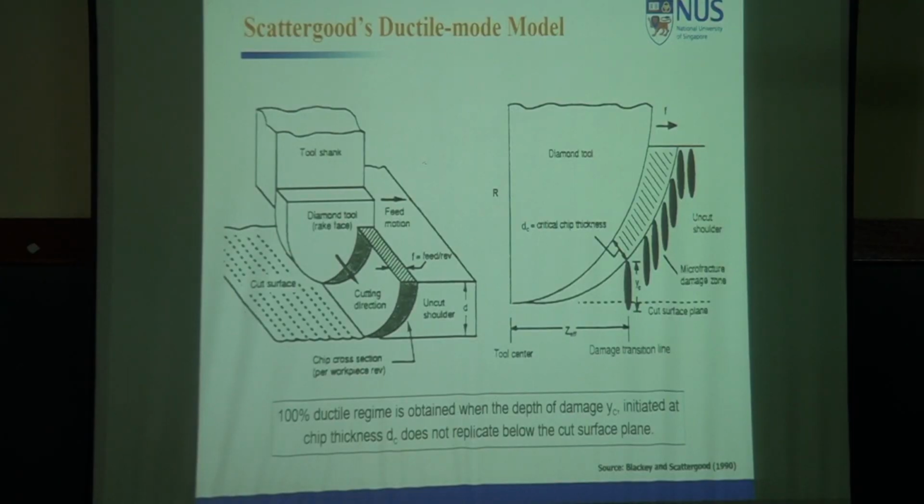In brittle material, you have to control the feed rate and depth of cut very carefully, then you can machine brittle material. I'll show you later that the compressive stress is so large that it takes over from fracture. So it doesn't allow the fracture to take place.